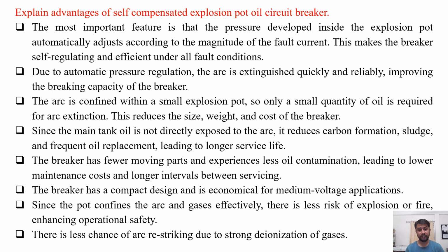Since the pot confines the arc and gases effectively, there is less risk of explosion or fire, enhancing operational safety. There is less chance of arc restriking due to the strong deionization of gases. So these are several advantages of self-compensated explosion pot oil circuit breaker.